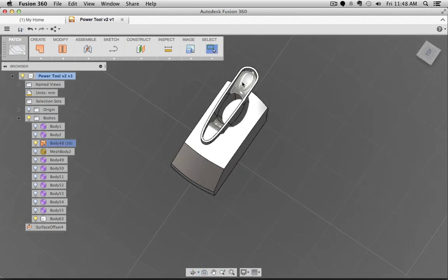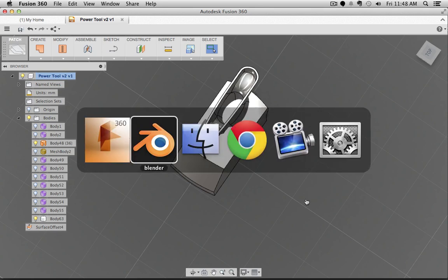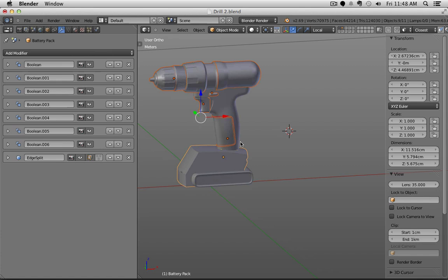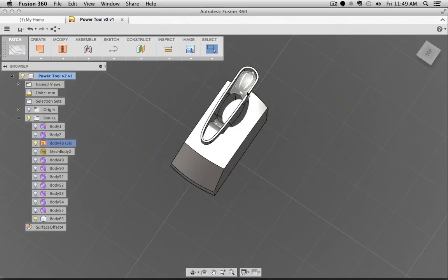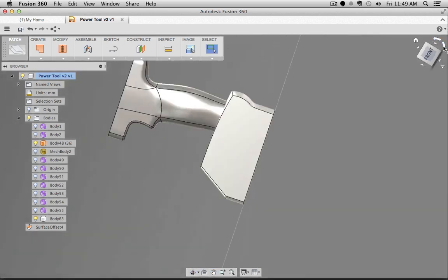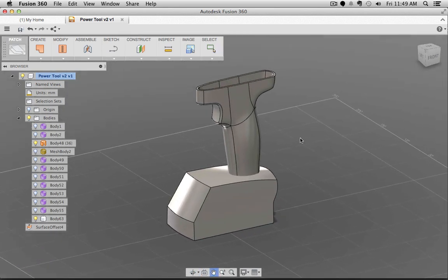So for example, the offset thickness I created here, of course, at that point was a little bit silly to do, but I just wanted to demonstrate to you how to do it, because you would, of course, completely finish everything, because you have to think about later how the different shells are being manufactured or injection molded. So I have to create a geometry that is defining a full part which should be manufactured, and then once that part is done, I create the material thickness. But that's something we will cover properly in a week or so, when we get ready to send the models to the 3D printer.